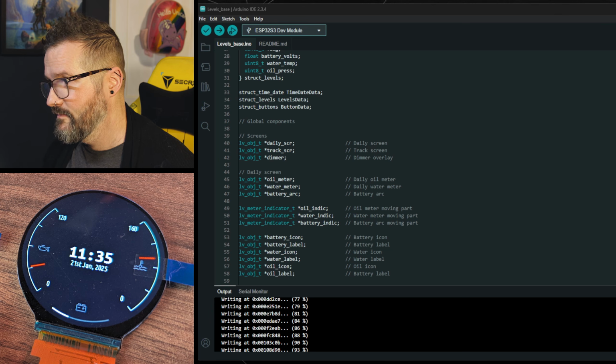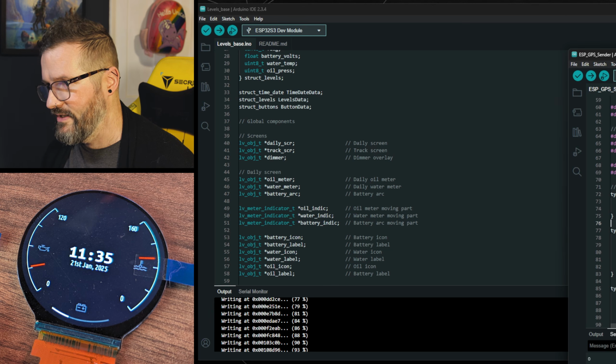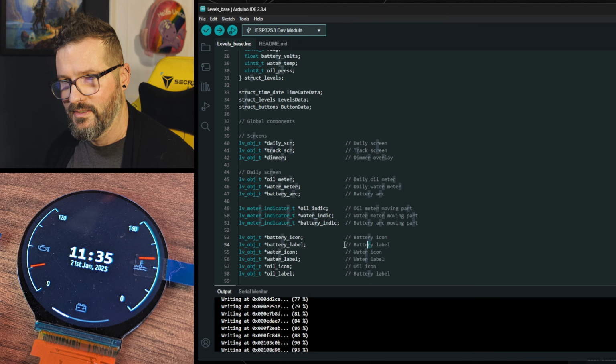That pin is now correct. I just need to quickly update the gauge so that gauge A has the signed versus unsigned int issue fixed and has the new way of receiving the oil pressure object, which it doesn't currently have. So in the levels gauge, we need to duplicate that structure. So the oil pressure structure here.